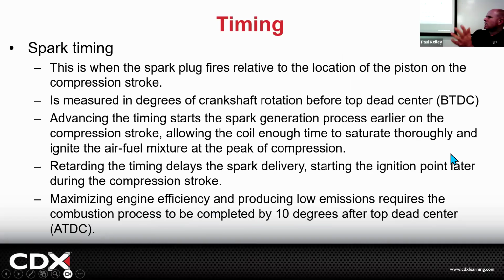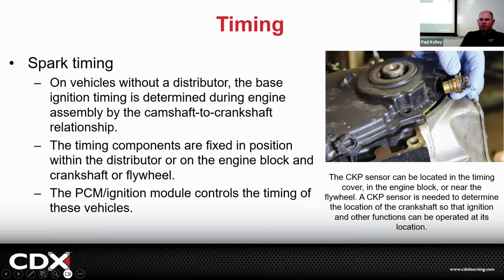So that means 10 degrees after top dead center, the combustion should have occurred. If we start it too late and we're not finishing until 20 degrees after top dead center, we're not going to get a very thorough combustion. It's not going to maximize our efficiency, and it's going to not have our lowest emissions possible. So that's why. Here's why and how.